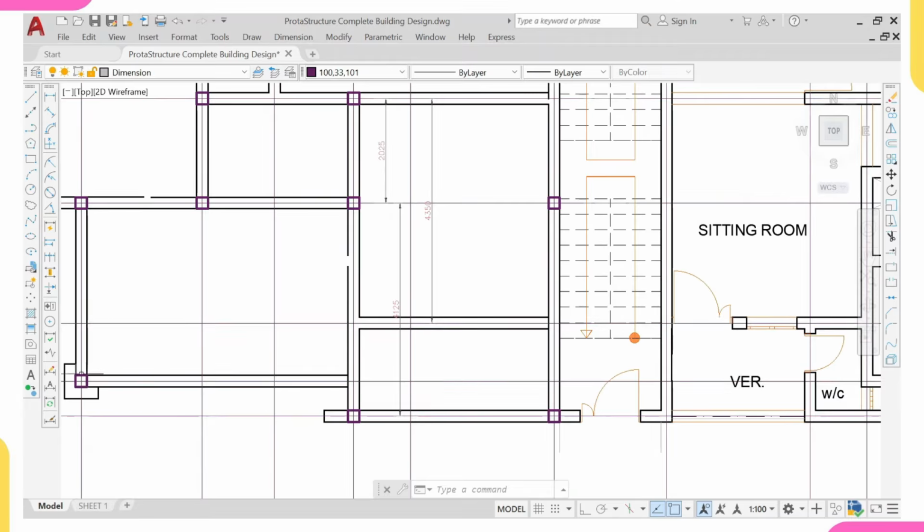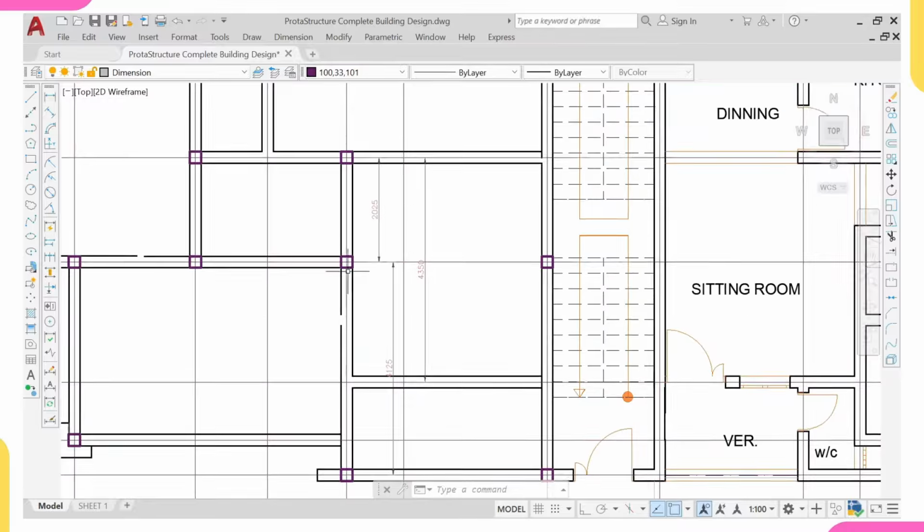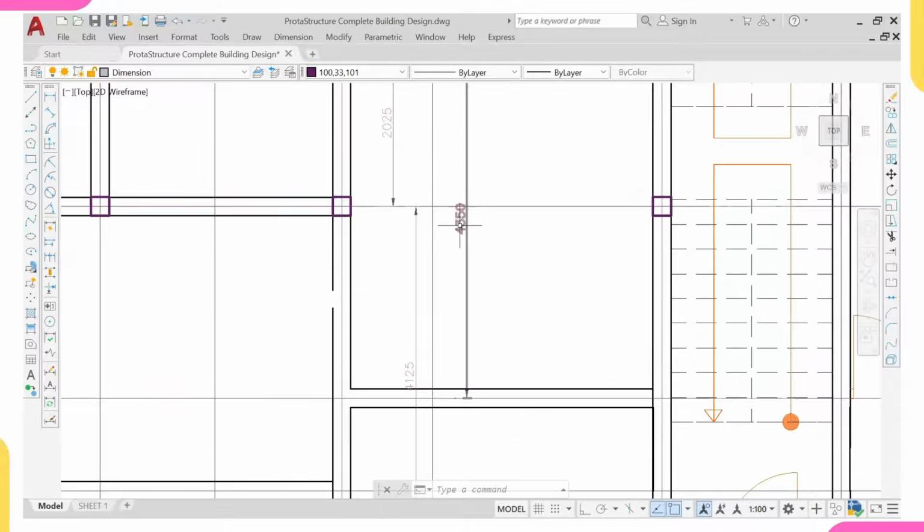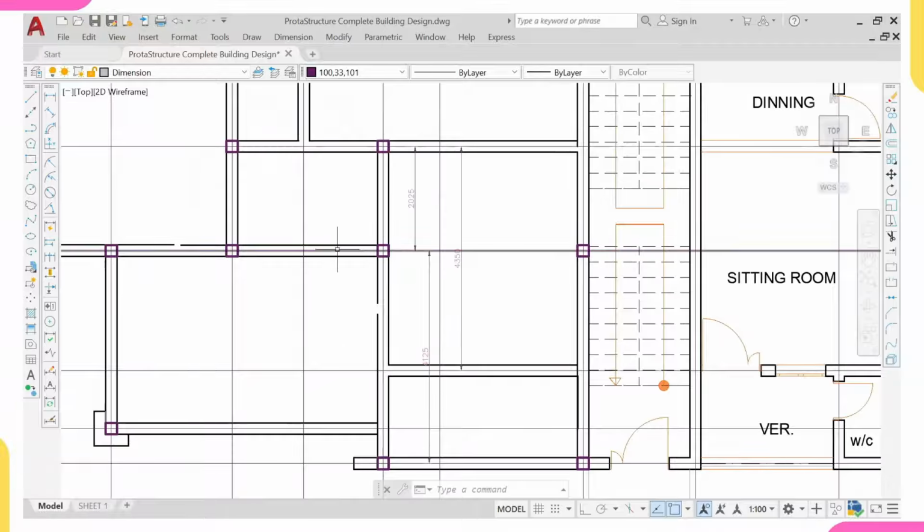So this beam now is carrying its load, like the slab load is transferred to this beam. Then this beam will now divide it into two. It transfers some to this column and then transfers some to this beam. So this beam now is a point load to this beam, and this beam is also carrying a point load from this. But if I should move this column to this point now, even though the span has increased to 3.25, it will now be carrying only 1-point load.